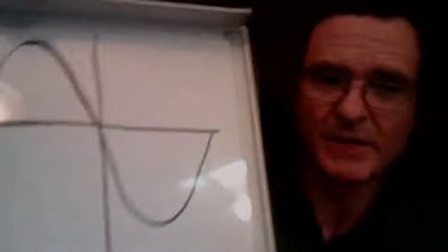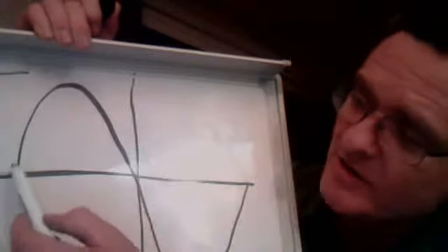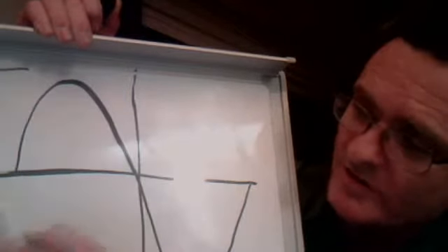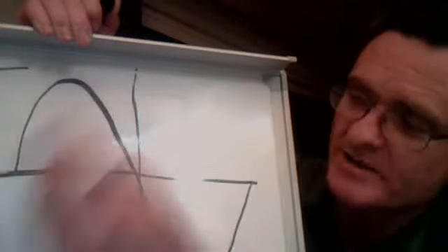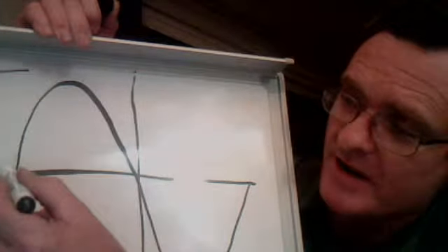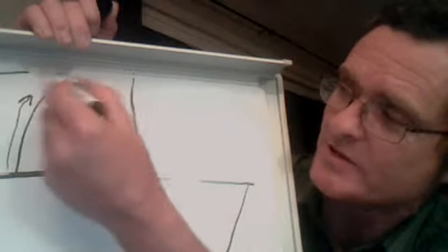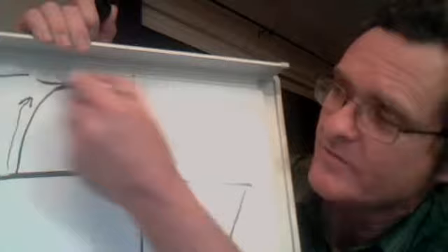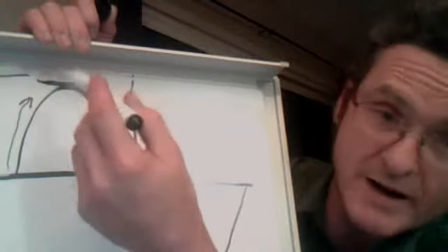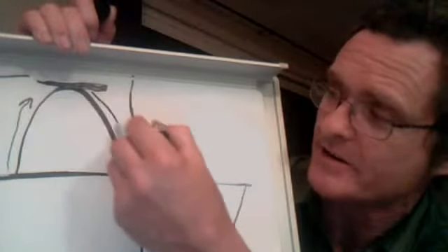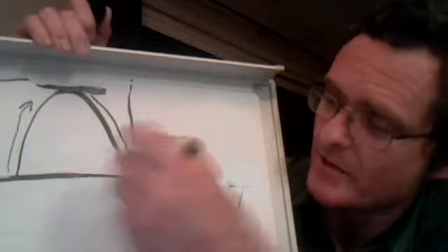Now when you're speaking about electrical generation on the graph here, as the generator starts out and the motor coil is the farthest away from the magnet, you are actually at 0 volts. But as the motor spins and the copper coils get closer to the magnet, the amount of voltage goes up until you reach what is the peak voltage. Now as the coil of wire moves away from the magnet again, your voltage approaches 0 one more time.